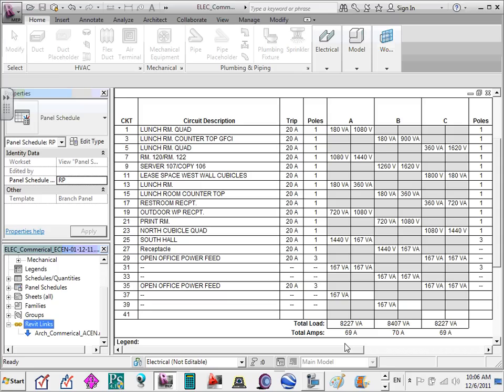The first thing you're going to go check, you're going to go to this Revit link and check here. I guarantee you will find the architectural file, your partner, troublemaker, went and deleted it or moved it. That's why I told you guys don't move it. Every time you link a file, it will drop your file right in here. So if you go there and you can't find your model, please go check there and make sure. It will tell you it's not there. So what do you do after that? We will relink it again. I'll show you how to relink.